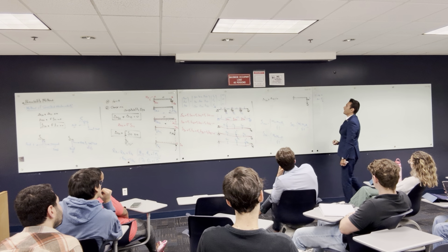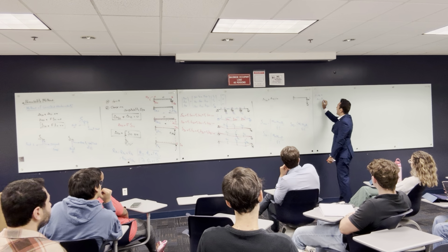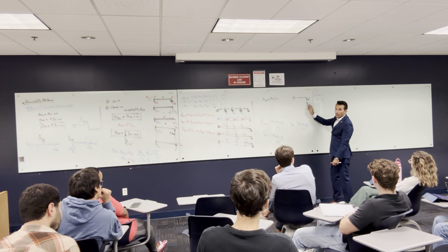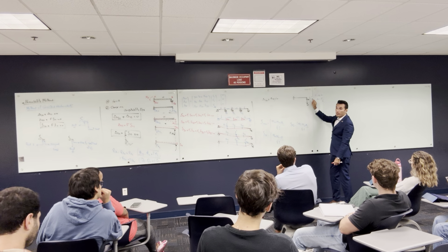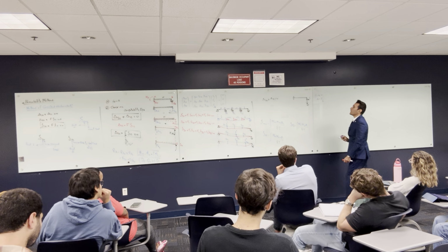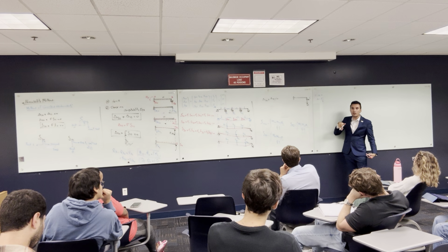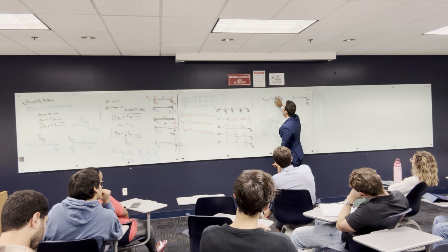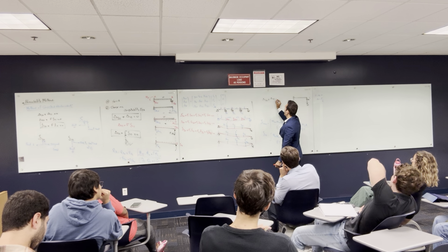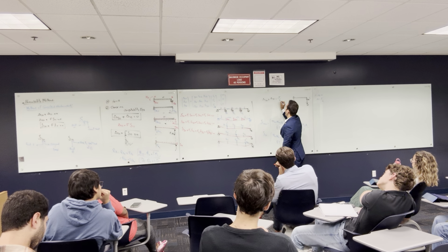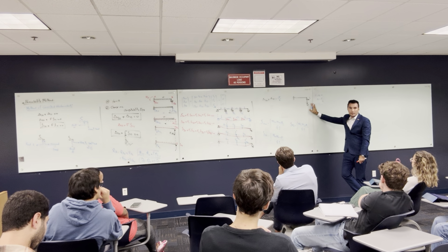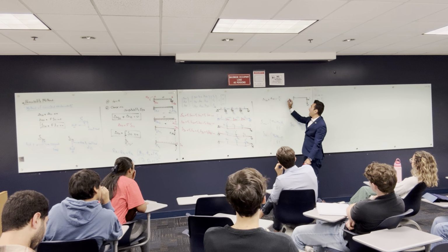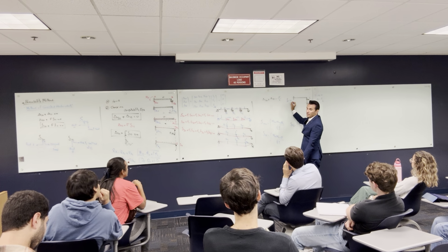F over K. Alright? But I'm gonna put negative here. Why? Because the force that I want to find out is a reaction, not the internal force, and the delta is in the opposite direction of the F. So I'm gonna put negative because always in a spring, the delta is gonna be opposite in the reaction direction. So rather than having 0, I'm gonna say that this is gonna be equal to negative F over K. And definitely in the problem, I'm gonna give you the stiffness of the spring. If the stiffness is infinity, what is the value here? It's gonna be F over infinity, which is 0, right?